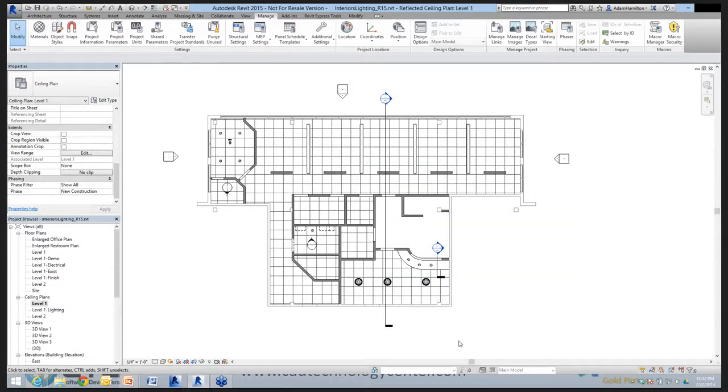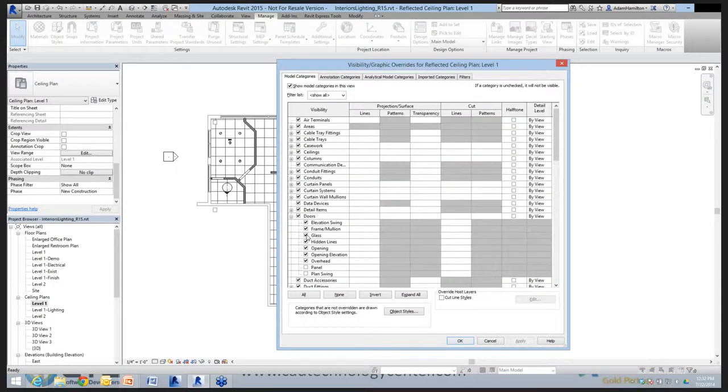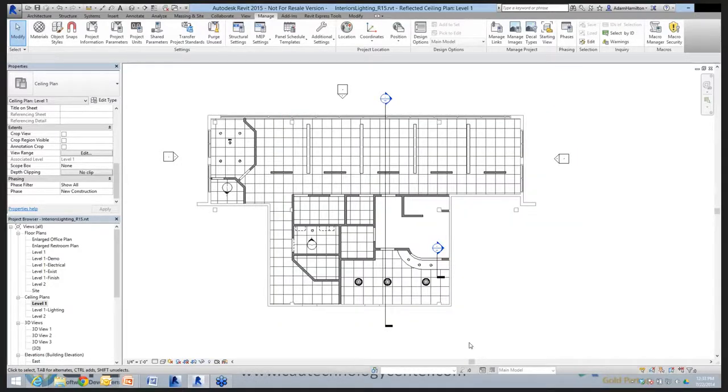It's important to note that if there were things such as glass inside there, those would need to be disabled as well. So we have these same settings that may be shown in elevation but also shown in plan, but we have to make sure that we turn off the elements without turning off the door. Okay, so utilizing the view range and modifying things such as the subcategories of the visibility graphics, we're able to get these views to look how we'd like as well.